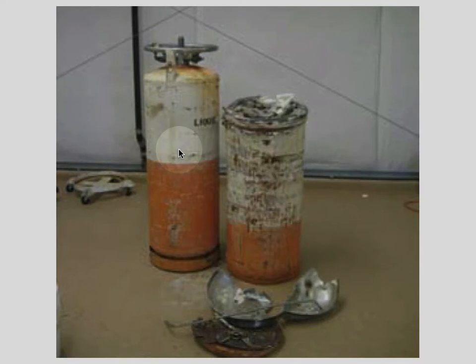Here's a photo of the cylinder itself that underwent the explosion. What happened in this particular case is, you can't see it here, but there's a cylinder inside a cylinder. The inside cylinder leaked into the void between the inside cylinder and the outside cylinder. That's where the pressure buildup occurred. The ends of the cylinder were not able to contain that pressure, and the lower end of the cylinder failed first. That launched the cylinder vertically upwards until it hit the ceiling of the lab in which it was.